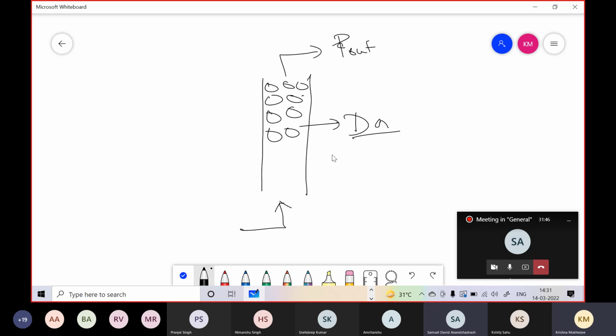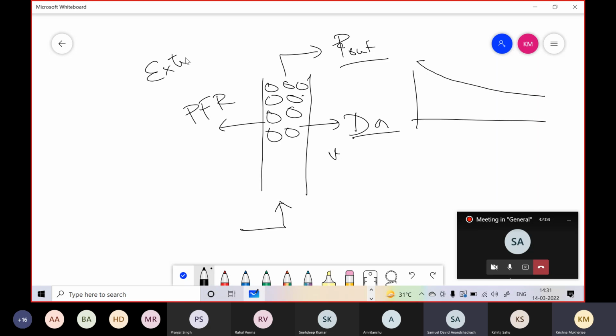And this will change depending on the velocity, etc. And this P out will change, which will drop in a certain way given my deactivation kinetics, which I have determined from the CSTR.